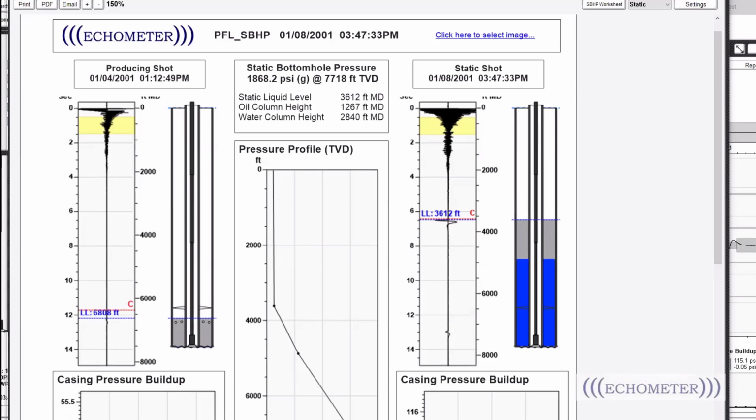Okay, Jonathan's asking if we can send an Excel that I showed. Well, just a quick Excel. It shows the static shot, no need for multi-phase S-curve calibration, right? Just assuming pure water and oil and no gas in liquid. Well, the calculation, Jonathan, is related to a static well. So yes, there is no gas in the liquid right now. You have a gas column on top of that, but then you have oil and gas based on, as we said before, the previous fluid level shot on the producing condition and the well test information.